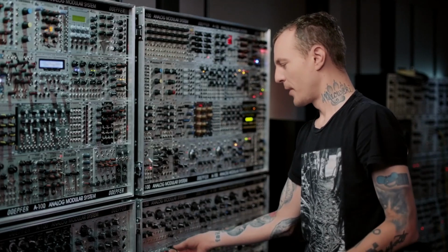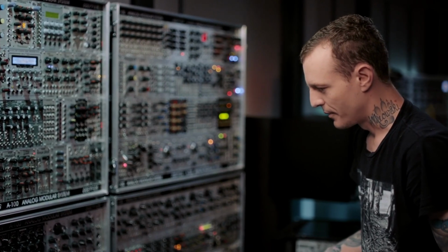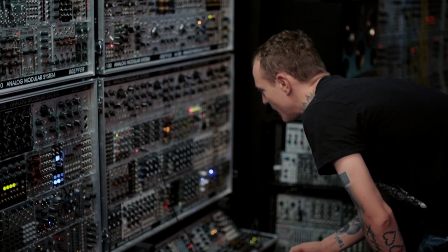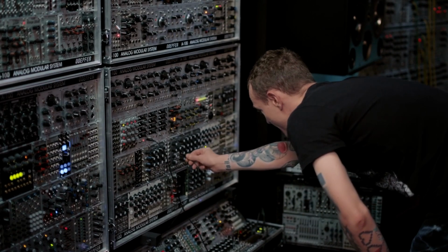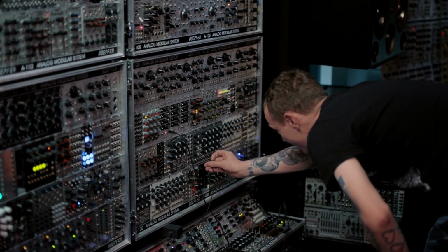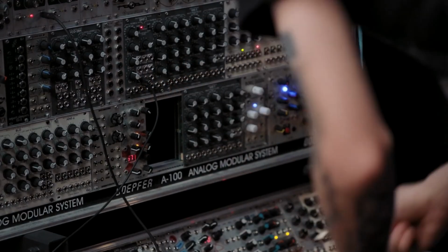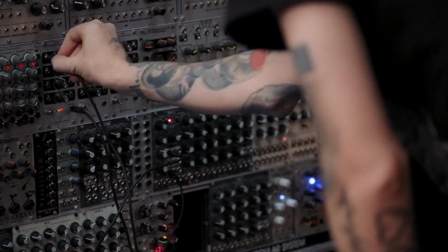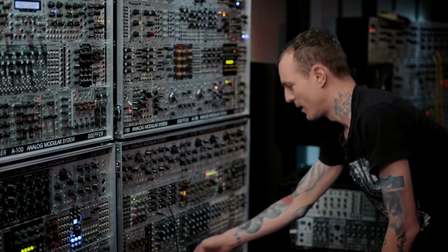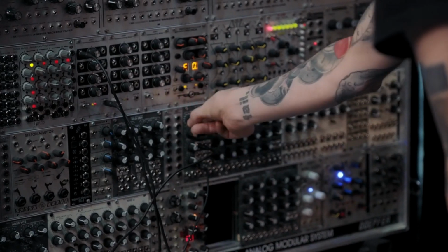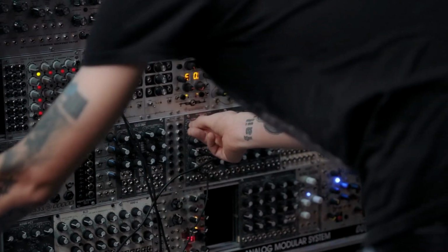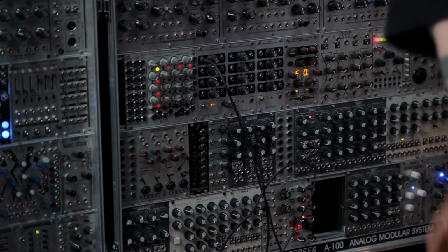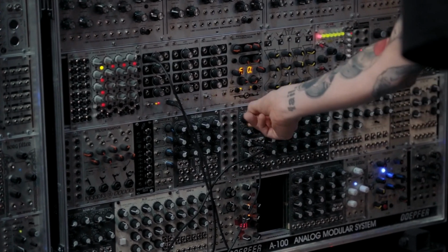So instead of going into that, I want to go into a low-pass filter. You could take any filter you like. Let's say this one here. I'm going to take the output of that saw wave and insert it into an audio input of that filter. I'm going to take the audio output of that filter and then go back to my output. So now I'm just going from here to there to there. You just follow the wires. So now I'm controlling the filter cutoff. So now I have a parameter that I can change.